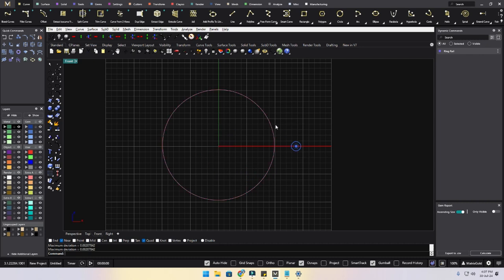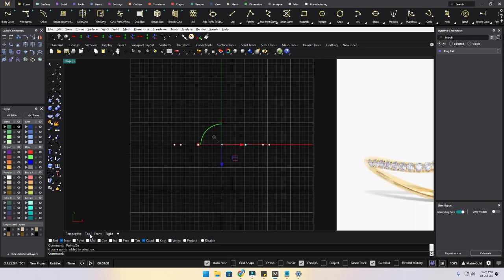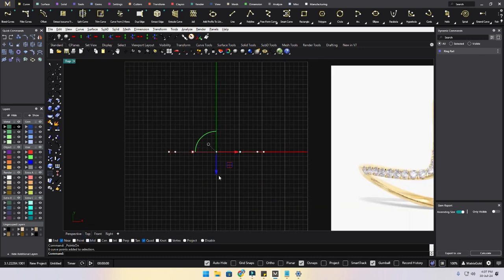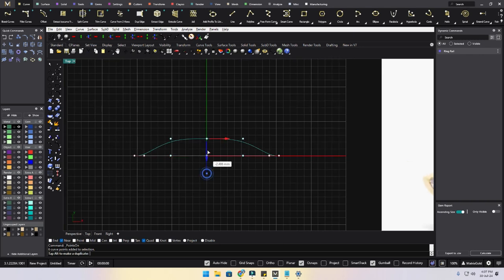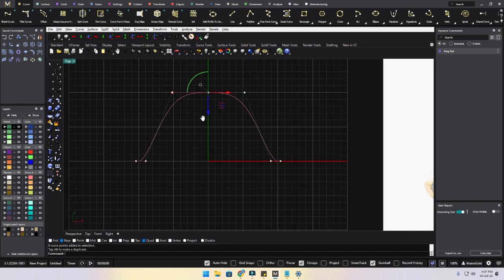Once we have done this, we are going to select this part, F10, and remember to select the upper 3 points over here and the bottom ones. So we are going to select all the 6 points over here. We are going to go in front, and what we are going to do is drag this part till, so over here I have taken 10 points for this one, 3 points.